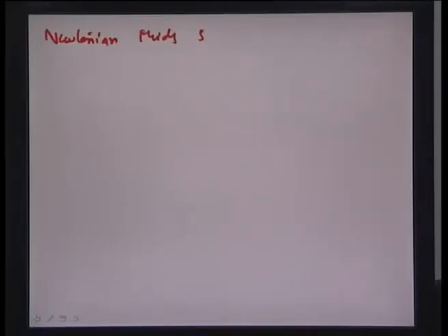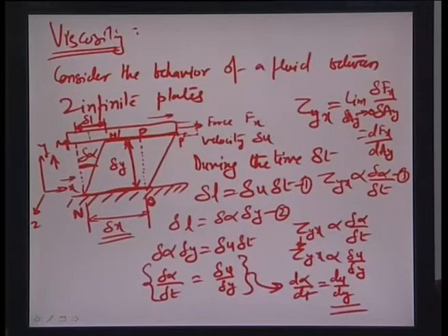So, let us define this again here, that in Newtonian fluids, and we will in just about a minute see what happens in the non-Newtonian case and how that is different from this particular illustration, the shear stress is also directly proportional to the rate of deformation. As we have illustrated here before, I just forgot to mention that this proportionality only holds valid for Newtonian fluids.